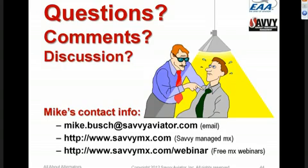Okay, and Jim would know, what's the cost of a rebuild and the cost of a new alternator? Well, it varies all over the map depending on the capacity of the alternator. For example, on my Cessna 310, which is a known ice airplane, I have 200 amp Prestolite alternators, and overhaul exchange cost on those alternators is about $1,000. I wouldn't even hazard a guess what a new one would cost, but it would be more than I would be willing to pay.